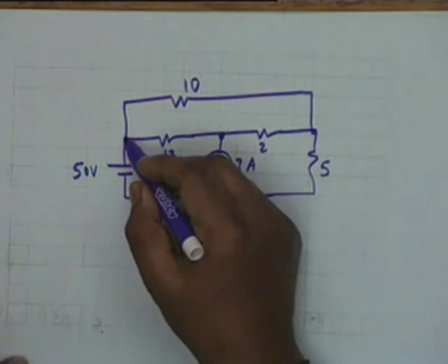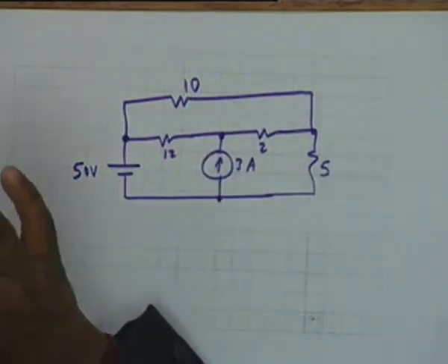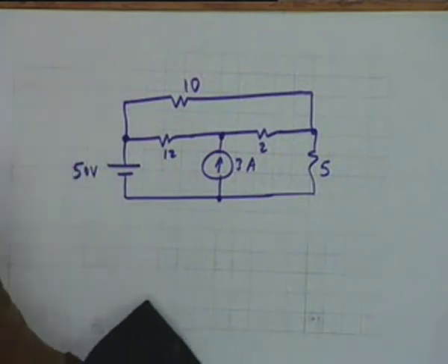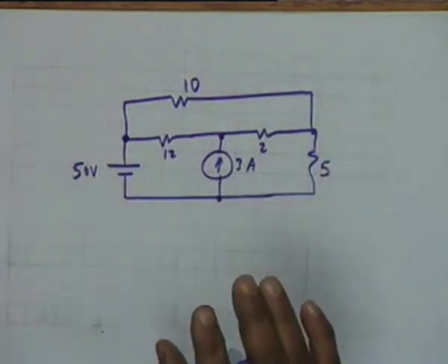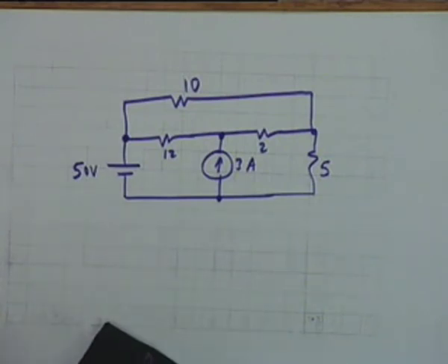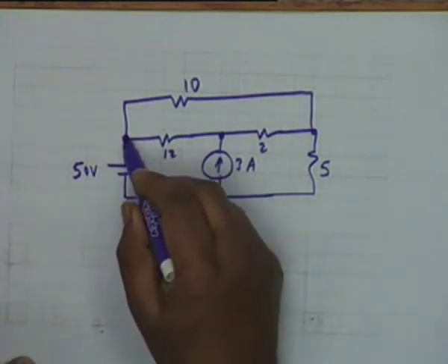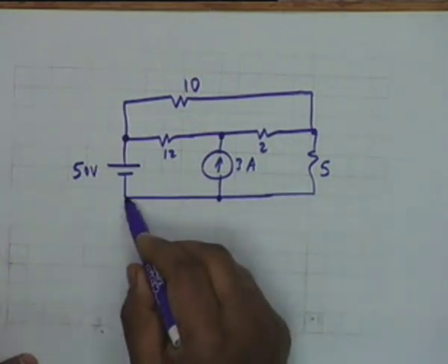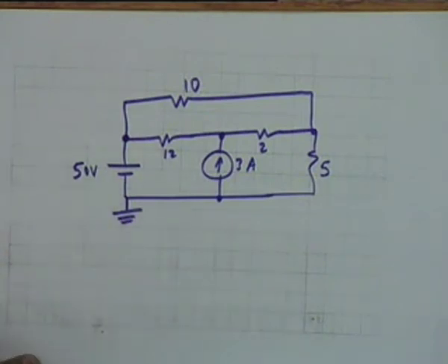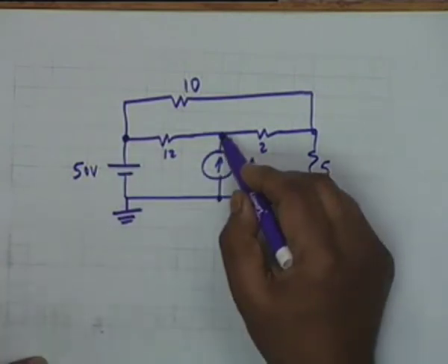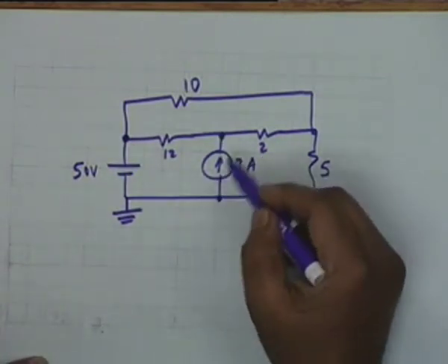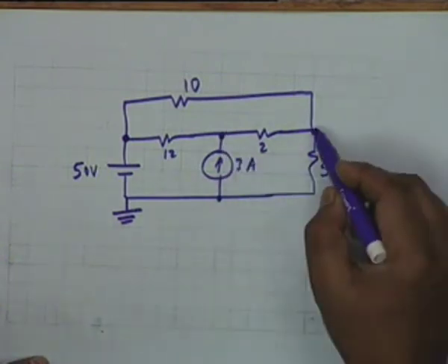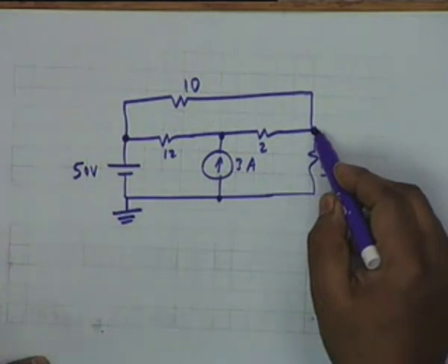that if we know, we were trying to solve these circuits for the currents. We wanted to find all the currents. Suppose instead of currents we find voltages at each of the nodes. The voltage here is obviously 50, we know this because it is connected, and this is a common point, this is a zero potential point. We could consider this as grounded or zero potential. So this node voltage is 50, this node voltage we do not know, it is a current generator, we do not know what this voltage is. We also do not know this node voltage, another node.